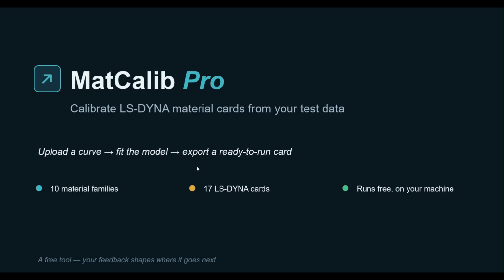Hello everyone. I wanted to show you a tool I've been building which I call MatCalib Pro. It does one job. It takes your material test data and turns it into a ready to run LS-DYNA material card. So if you have ever sat there converting engineering stresses to true stresses by hand, hunting for the right yield point, and then lining up the keyword fields one column at a time, this tool is meant to take that whole chore off your plate.